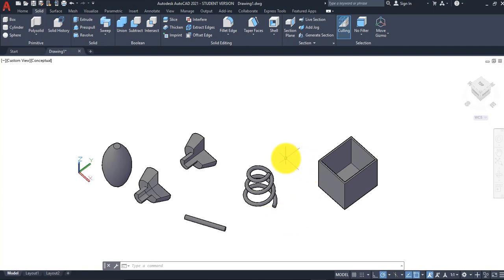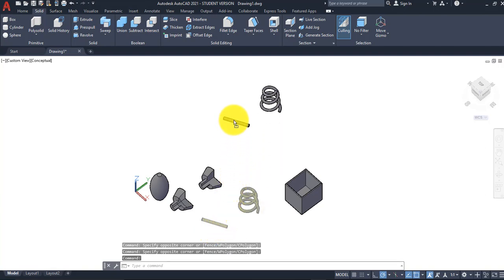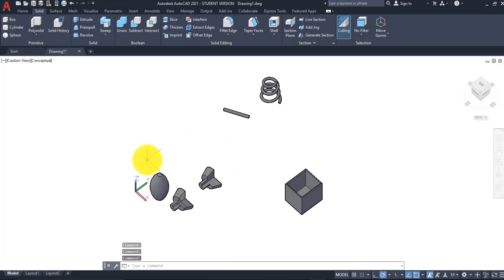So I'm going to select the sweep objects, hold my right mouse button down, drag them over up here, let go and pick move here. Then I'll do the same thing for loft. I'll select my loft objects, hold my right mouse button down, drag them over here and pick move here. So now I basically have those 4 shapes in different spaces here in my model space.